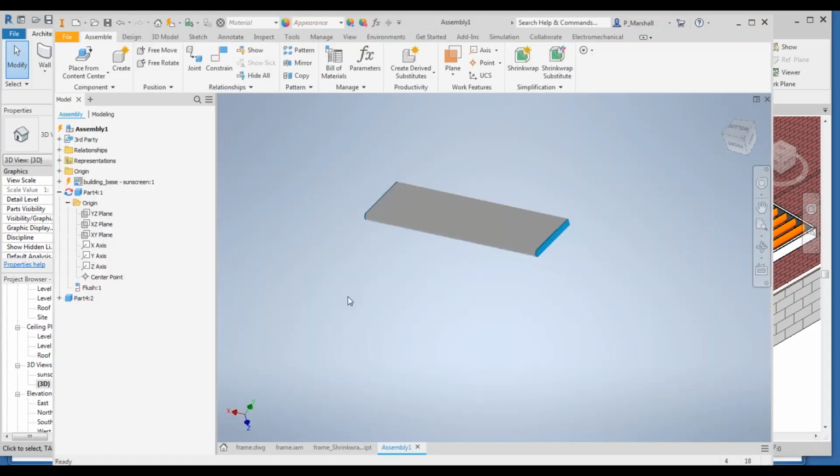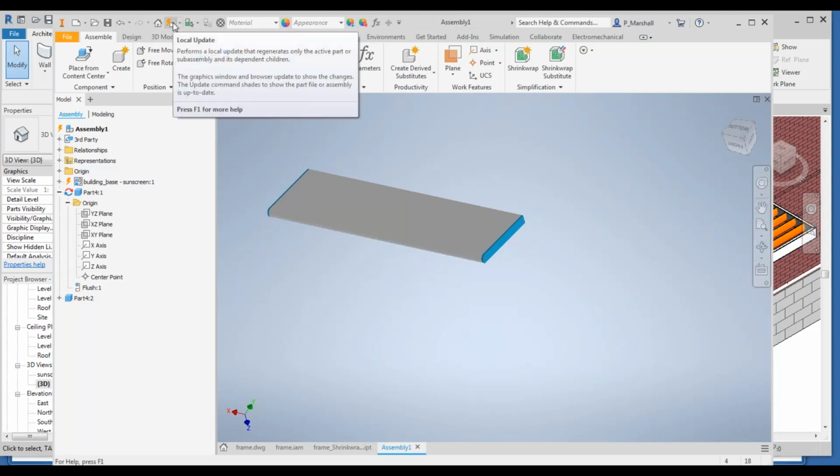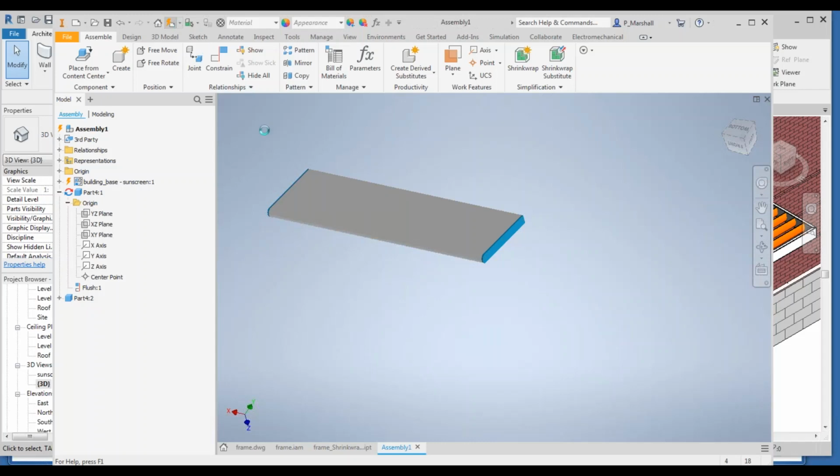and come back to Inventor. So the manufacturer has to update their file to accept that the architects changed their mind on what that sunscreen looks like. Well, because it's an associative model, because we got that data from the Revit model, there's an update capability. And I could say, go back to that Revit model and update this model to match. And of course, the geometry changes, the end plates change because they're also forced to be the same size as the design. And now everything is updated.